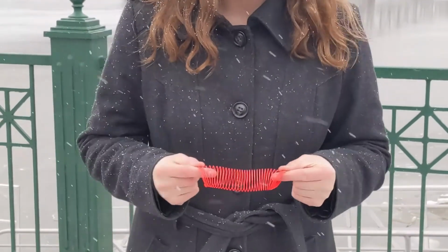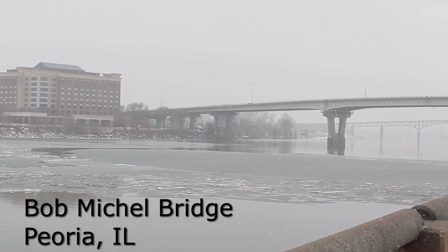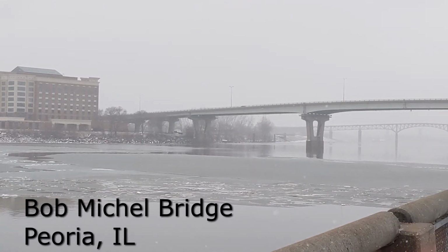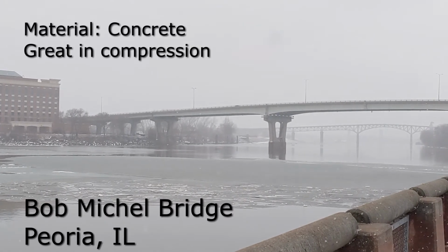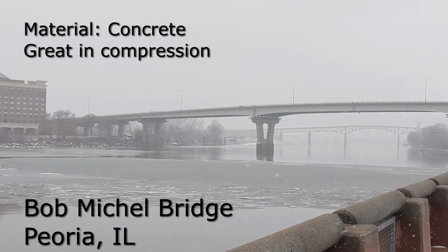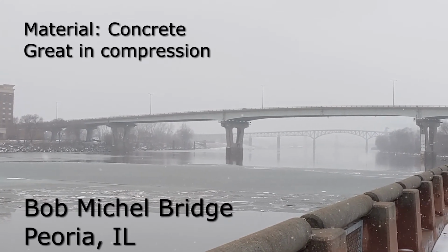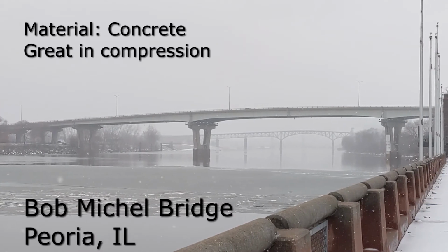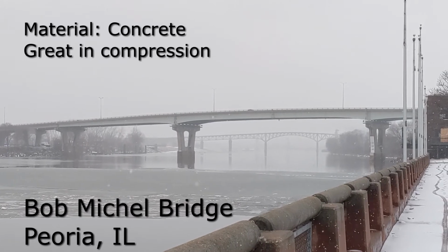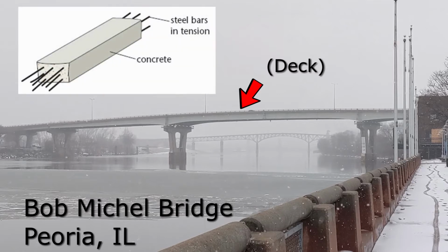But what if we scratched the slinky idea and we tried using a material that was a little bit stronger? You can see that some bridges are made out of concrete, and concrete is really good under compression, but it's not so great in tension. Concrete is made up of sand and mortar, which is basically a glue that binds all the sand together. And just like when you make a sandcastle, it's a really good material for taking squeezing loads, or compressive loads, but it's not so great in tension. So sometimes when you see concrete used on the deck of the bridge, which is the freestanding part, you can assume that concrete has been reinforced on the inside with steel bars to make it stronger in tension.